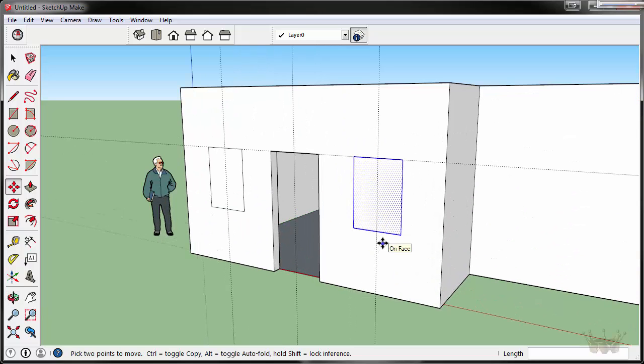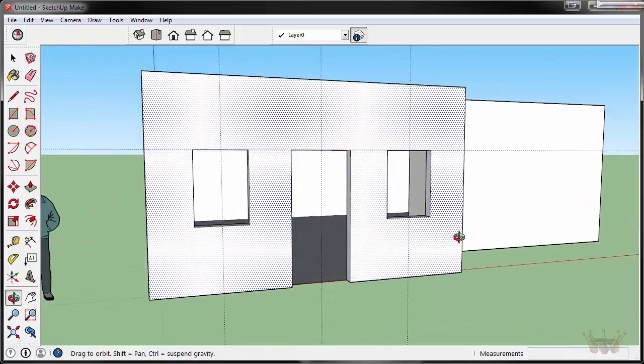Now we'll push-pull the openings using our push-pull tool, which should have remembered the distance of the last opening, so we should just be able to double-click in both instances and automatically cut out the lines we need.